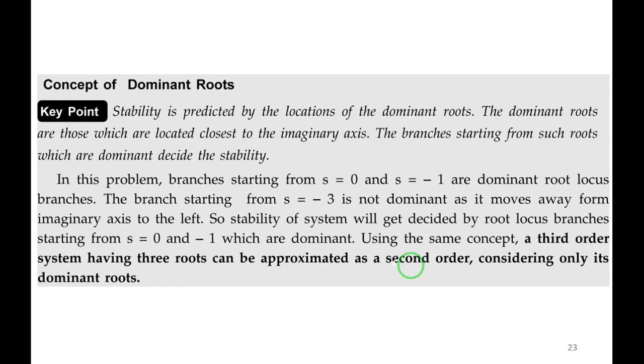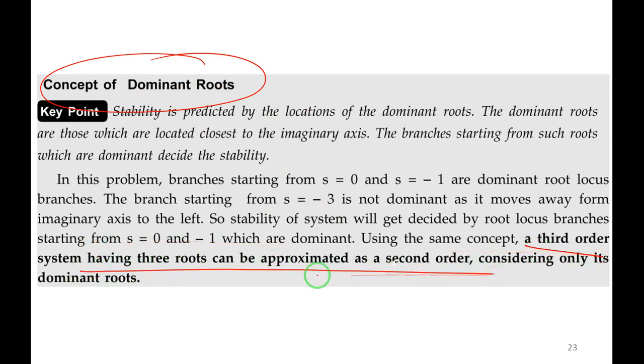The concept of dominant roots I have already told. Dominant roots are those which lie very close to the imaginary axis. The concept of dominant roots helps us to convert higher order systems to lower order systems. Here I already told you a third order system gets converted to a second order system, because we are neglecting the term s plus 3, if you remember. This completes today's lecture.